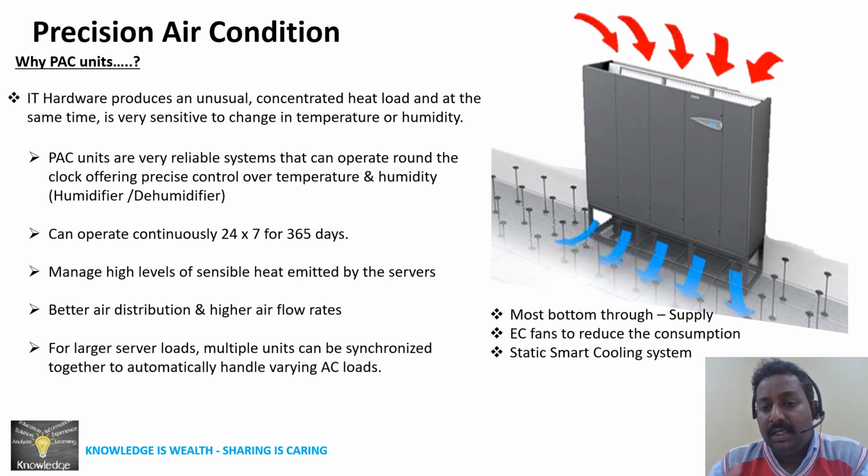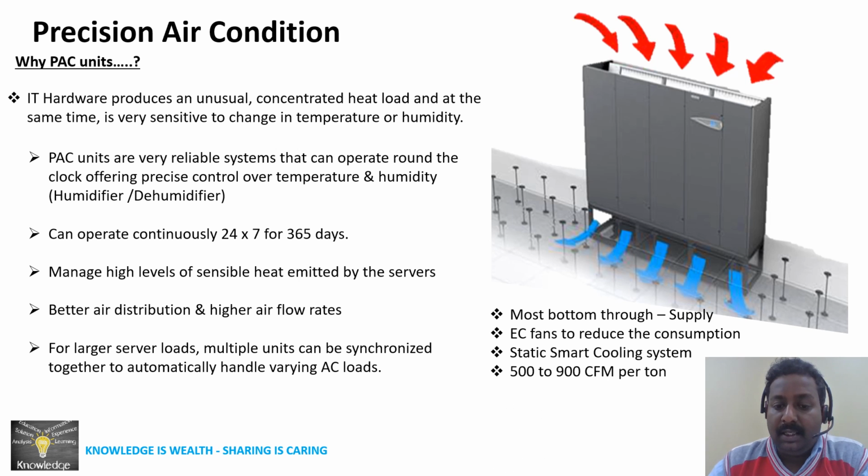where, based on the return air temperature, it will control fan speed and actuator positions. And as I already told, unlike comfort cooling at 300 to 400 CFM per ton, the design of PAC can go up to 500 to 900 CFM per ton.